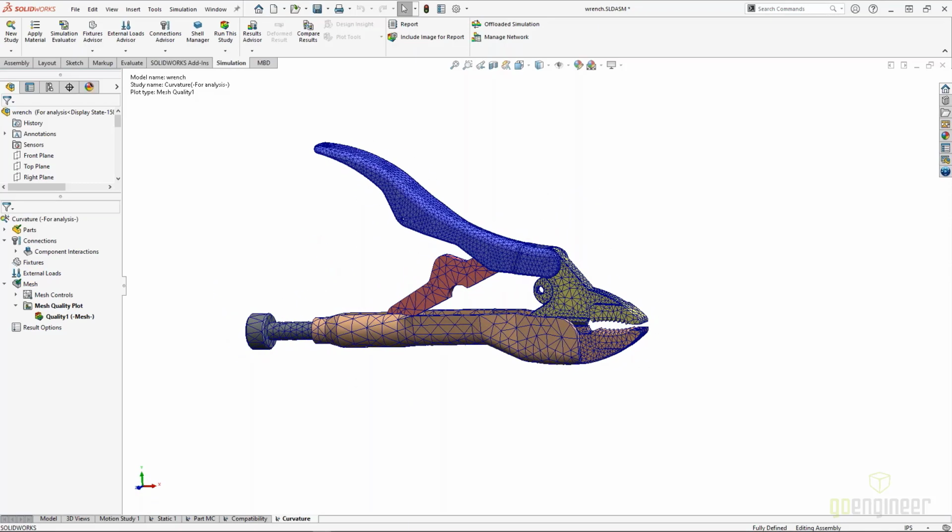So there are three different methods of approaching mesh failures in a model. One is to go in and add mesh control to individual components or to faces where two components come together if your nodes are being shared. The other option is to turn off those nodes being shared, change your compatibility, and undo the enforced common nodes.